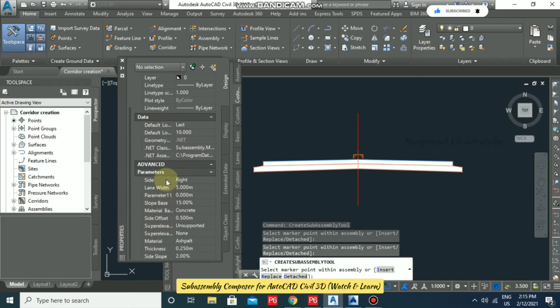These are all the parameters that we have created there in Composer. Do you remember everything we have here? So this is what is important. Okay, like this we can go for customizing our lanes. This feature is helpful for people who are working in the transportation and highway sectors, where they will have many things like bases, sub bases, and then shoulders, daylights, everything. So they can make use of these parameters, and they can make use of the Composer as well.